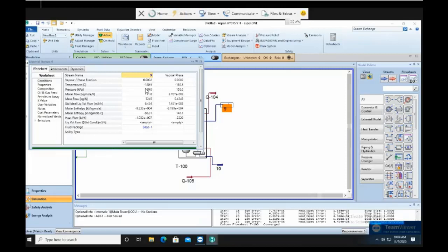So when you want to do that, you can make the pressure a vacuum, meaning less than 1 bar, like 0.5, 0.3 bar, something like that. With that, the boiling temperature will go down, especially for heavy compounds. So you protect your compound at the bottom of the distillation column. That's the reason why we use a vacuum distillation column. I think you have learned these things before.